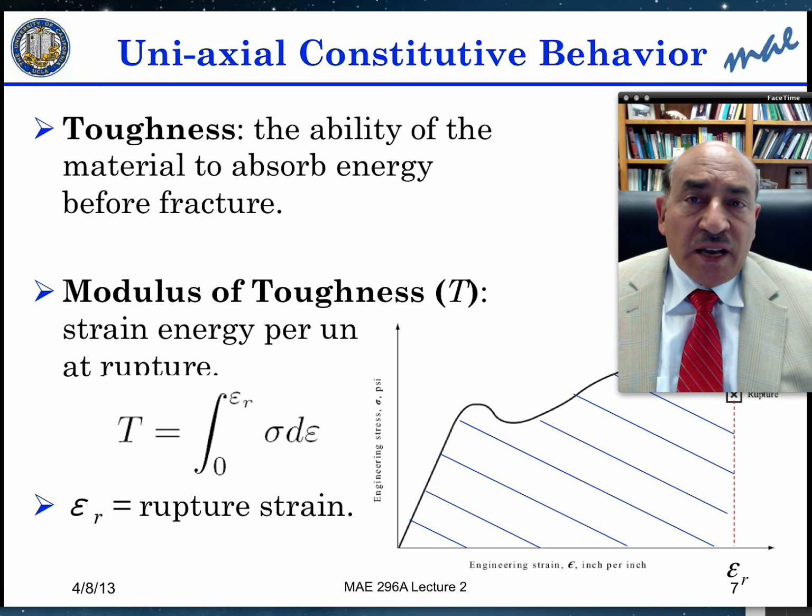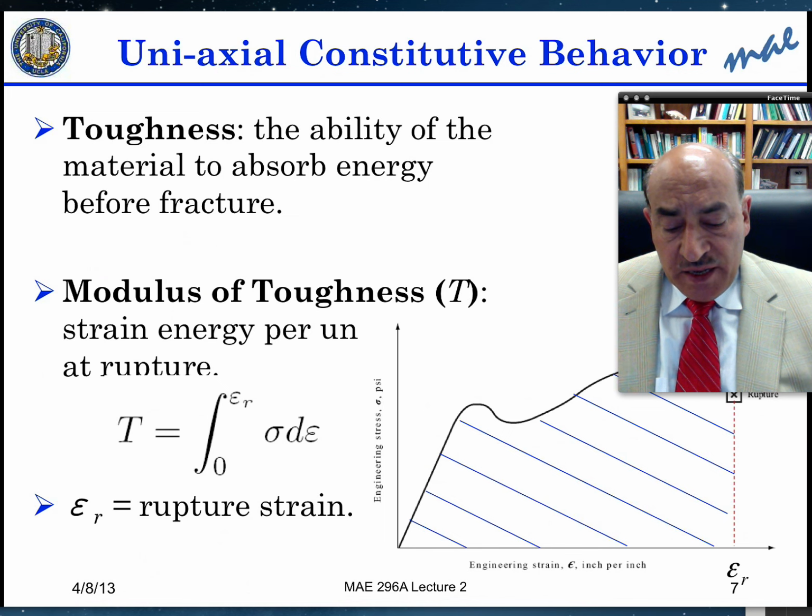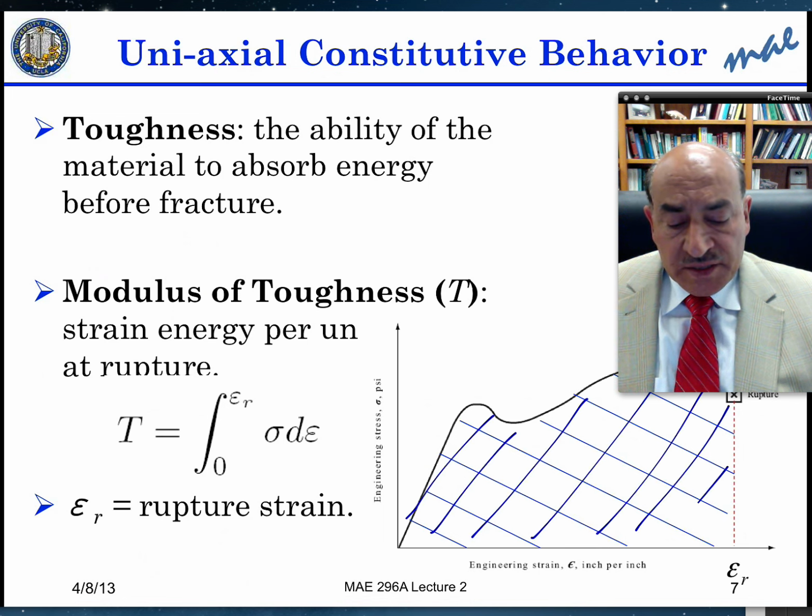If we consider now the entire deformation process, say in a car crash, it is important to absorb as much energy as possible all the way through plastic deformation. We're not worried about fracture or anything of that nature. We just want to absorb as much energy as possible. Then we must take the area under the entire curve, both in the elastic range and in the plastic range.